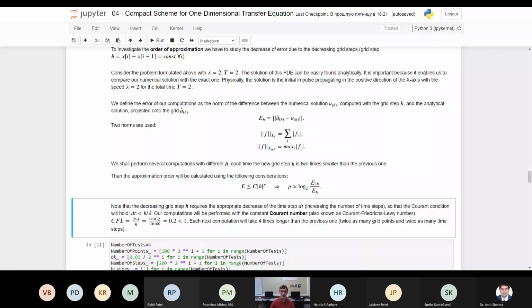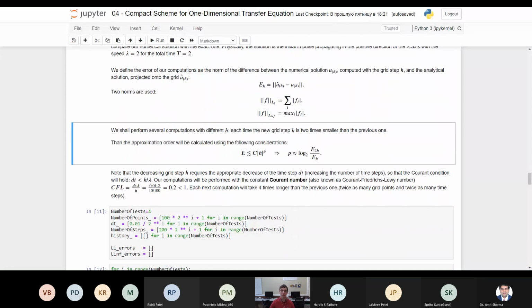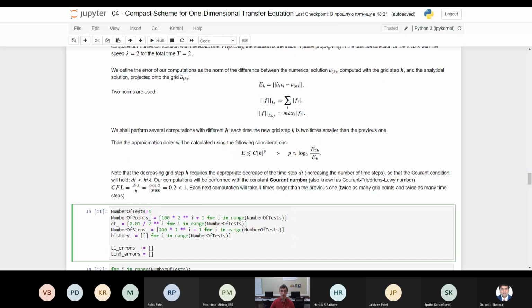And the higher this value is, that means that the errors decrease quickly with the diminishing time steps, and it results in the fact that running the simulation with the same number of points in the mesh and the same number of time steps, but with different schemes and of different order, we can significantly improve the quality of the numerical solution.